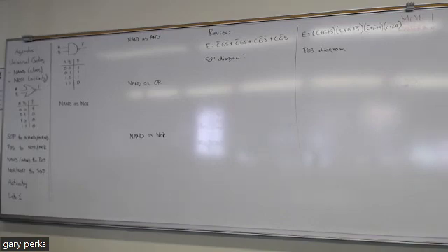And same thing with the NOR. With the NOR, you can make a NOT. With the NOR, you can make an AND. With the NOR, you can make an OR. And with the NOR, you can make a NAND. I'm going to show you how you use a NAND to make the other gates. And then part of the activity is for you to show me how you can use a NOR to make the other gates. So if you understand what I do up at the board here with the NAND case, you should be able to figure out the NOR case during the activity.